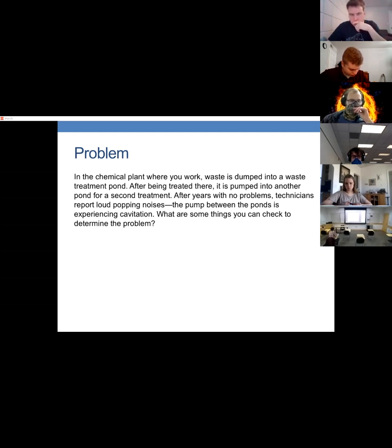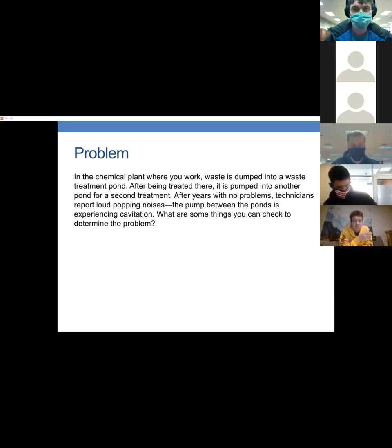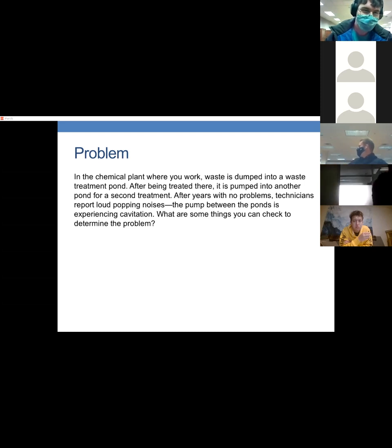Someone was raising their hand. I believe it was one of the Connors, but I'm not sure which Connor. Oh yeah, that was me. I was going to say that the epsilon must have increased because of corrosion in the pipe. Yeah, the epsilon, the roughness, could increase because of corrosion or something like that. So those are things I would definitely check. There's another answer in particular I'm kind of fishing for. Does anyone have another thought about something they could check?